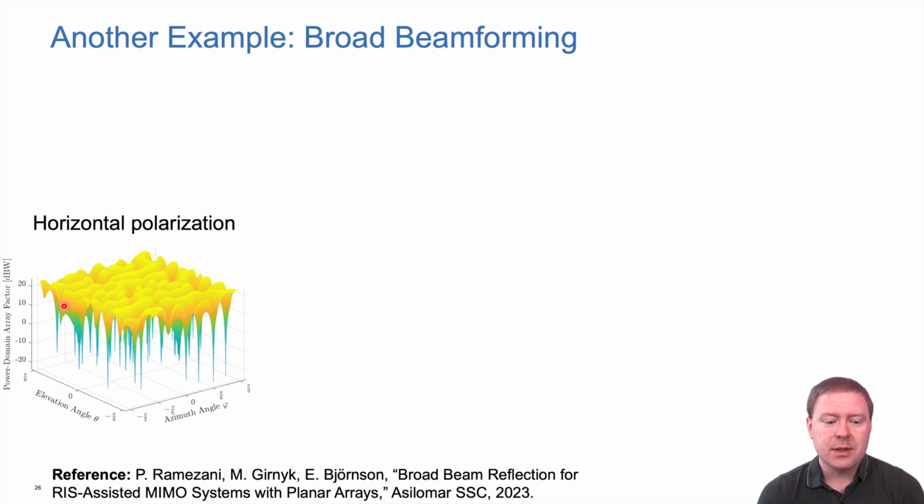And if we try to find an RIS configuration that spreads out the signal in all angles, both azimuth and elevation, so that we should have an array factor or gain in different directions that is constant, you will figure out that that is impossible. You will always have fluctuation up and down. Some directions are stronger and some will have nulls that really go down badly. So we can't do a broad beamforming with such an RIS without having nulls in it.